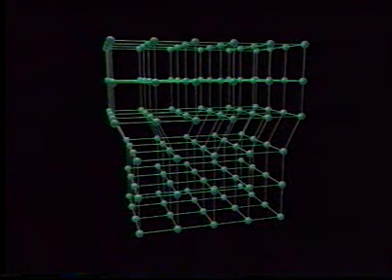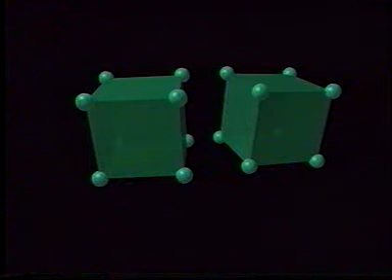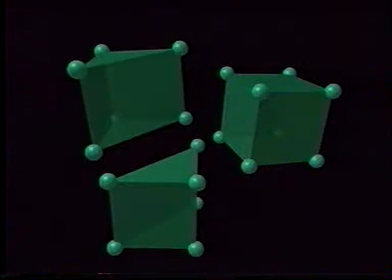For many years, X-ray diffraction techniques have been the most popular method of measuring residual stresses. The techniques are based on measurements of lattice strains. The strains cause changes in the spacing between crystallographic lattice planes.